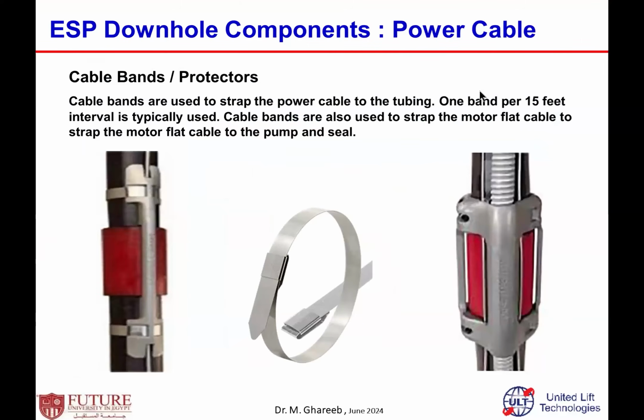Okay. We stopped at this slide before. We talked about the motor, the cable, the downhole cable. You can start the slide from the beginning, it will be better. Okay, sure. We stopped at this slide. We said the cable connecting the surface power to the motor has to be fixed to the tubing from outside of the tubing.